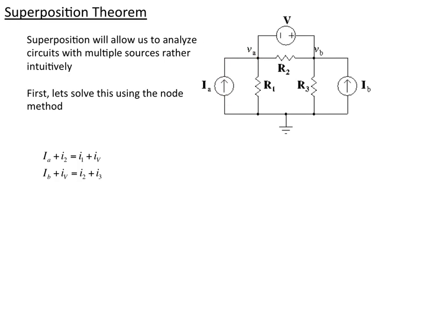And I'm going to say that the current flowing through R2 is I2 and that it's flowing this way. I don't write it down, but that's what I want. I guess I can actually draw it in here. That's I2 because it goes through resistor R2. And I1 flows this way and IV flows that way, from minus to plus through the voltage source.